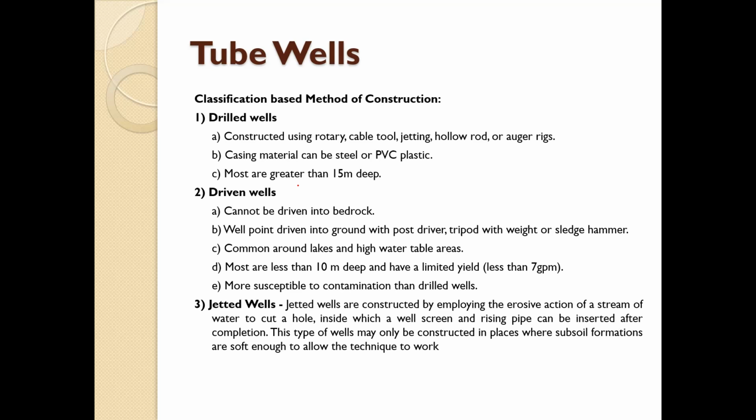Then the well around the common, around the lakes and high water table areas. So sometimes still you might have seen these methods on the banks of the rivers, or sometimes where we need to dig less, that is less than 10 meters deep. And for limited yield, there we can prefer this method. This is most susceptible to contamination than a drilled well because it has less depth, and sometimes a higher diameter also.